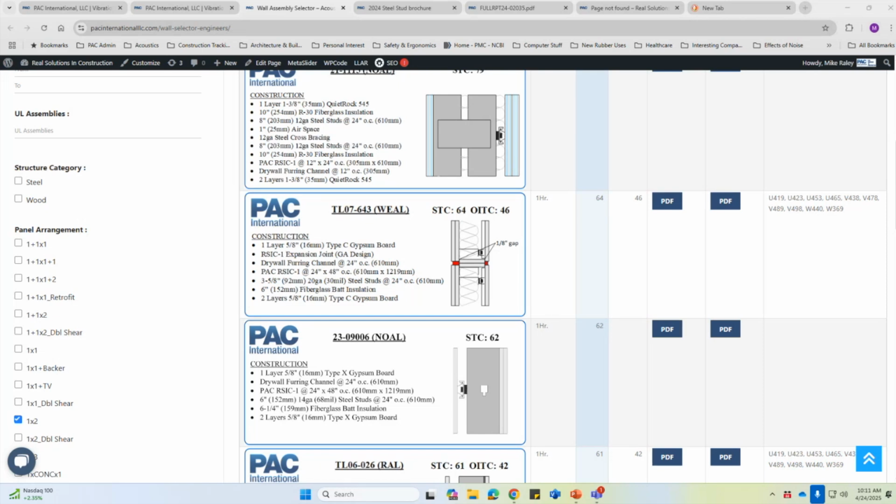And that does compress the fiberglass a bit, but the fiberglass is such low density because we're just using standard, I guess this would be R8 bat, but it's very low density. It's 0.5 pound or thereabouts per cubic foot. So you're not compressing it enough to where it starts creating some structural coupling, as far as I can tell. But there is, of course, a point where you compress the fiberglass insulation enough where it will create a structural transmission path from one side to the other.